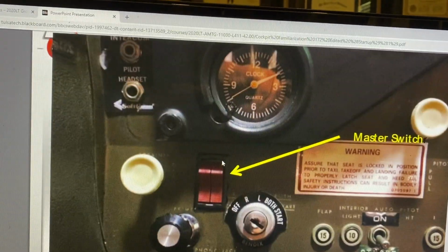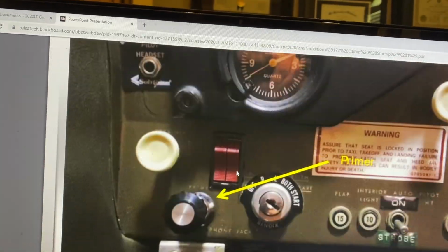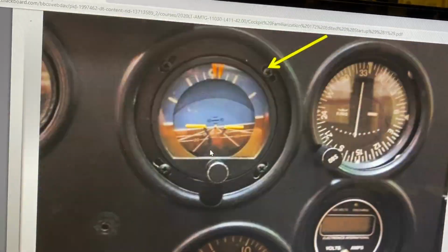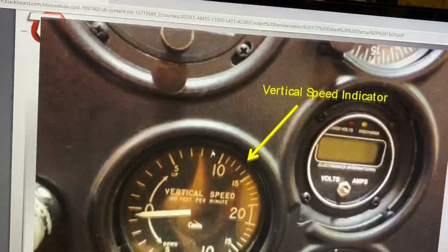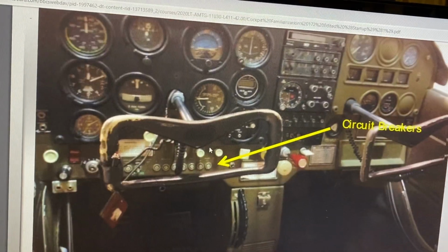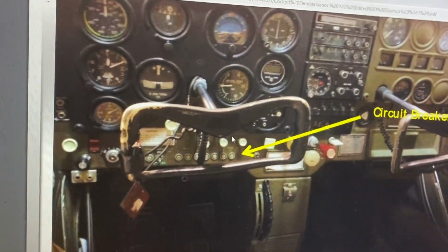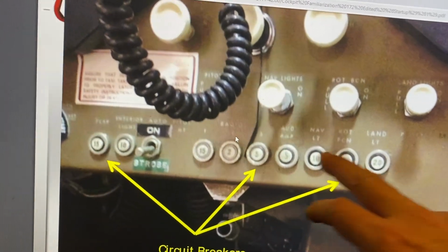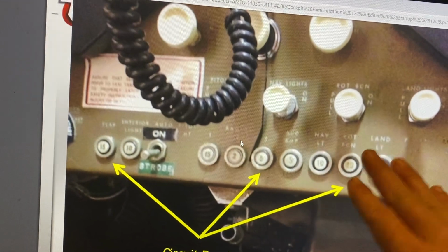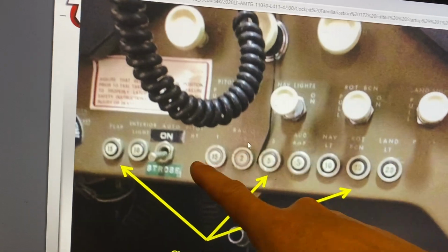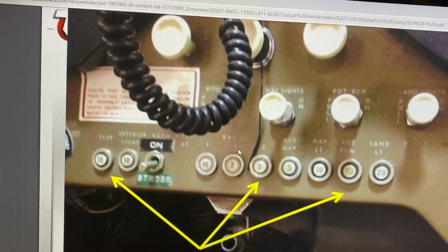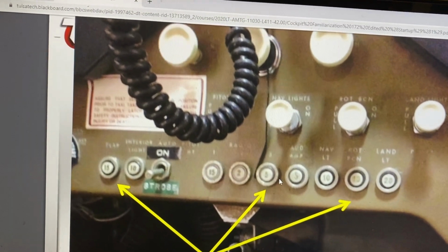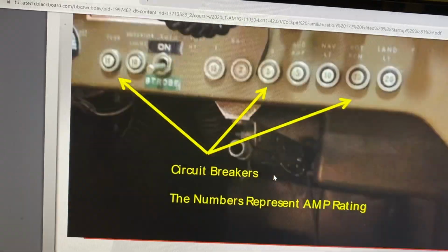Okay. The next things, this is going to go through each one of those items I just talked about. I'm going to skip these flight instruments and again go back to the part that talks about something we need to know to start the engine. So these circuit breakers there. On the checklist, it's going to talk about how to make sure those are all in. The type of circuit breakers they are, if they're flush with the panel, they're in. If they were extended out or popped out, then that would mean that there's something wrong with that circuit. So you would end up having to push it in and see if it stays in, or if it pops back out, and figure out why it keeps popping out.